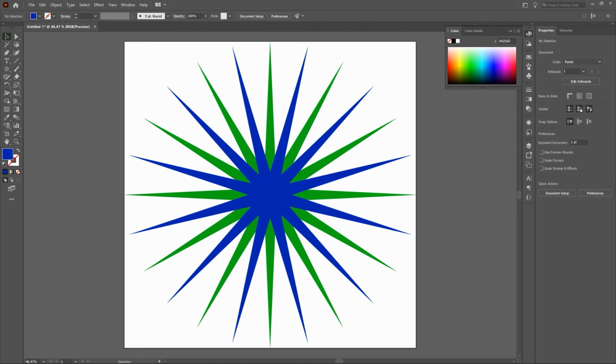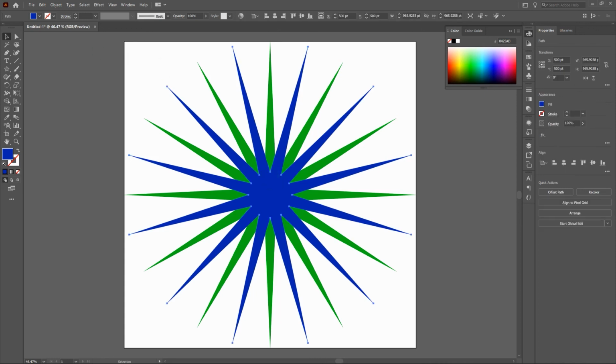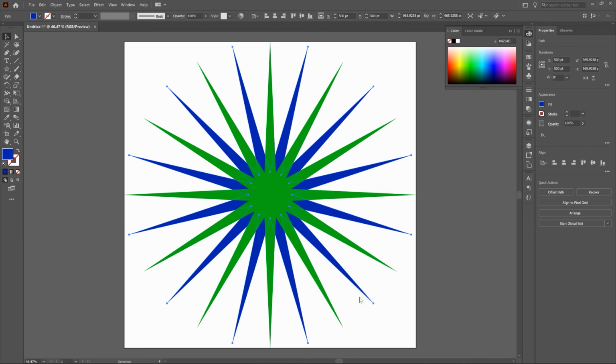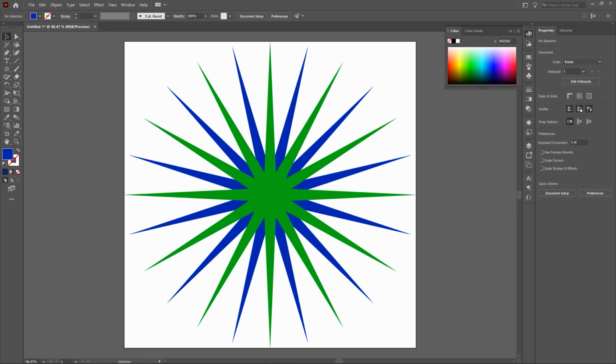Now that we've got our page set, you'll notice that we've got a small star and a small circle that are completely invisible. Now, if we want to set up our page properly with a single layer, what we could do is select each individual element, right-click perhaps, select Arrange, and then click on Send to Back, Send Backwards, or of course the opposite, which would be Bring to Front or Bring Forward. Not being able to see the elements, of course, makes it a little bit tough.